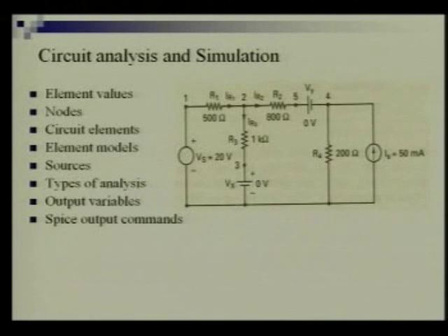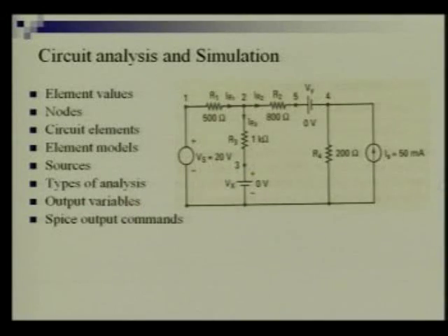Suppose this is a very, very small circuit where we don't have any active element, it is only the DC elements. So here you can see that we are giving nodes 1, 2, 4, 3, and the other node is not given, that is actually the ground node, that's the 5. And I'm sure you know that whenever we make the incidence matrix, we generally prefer the reduced incidence matrix, where the ground point you can just ignore. Whichever point you have ignored, the computer will understand that this is your ground point, fine.